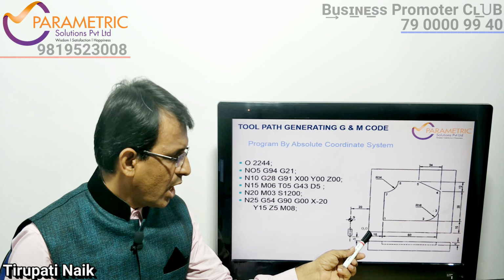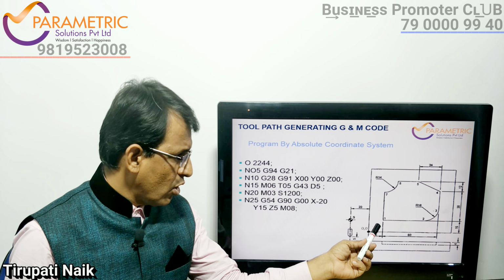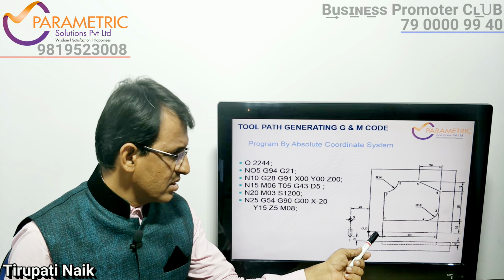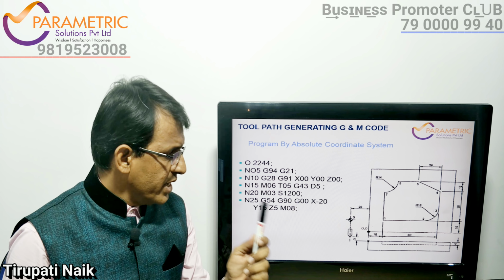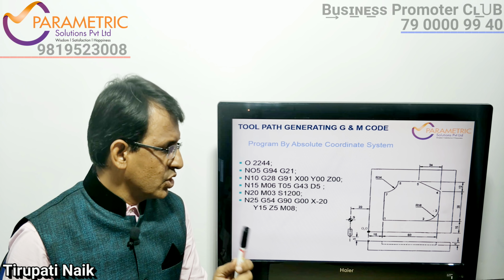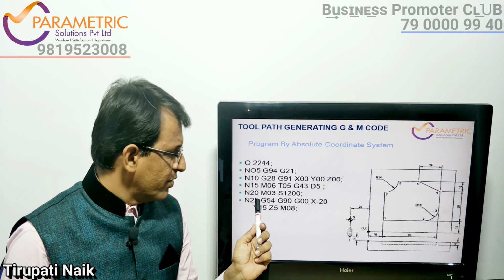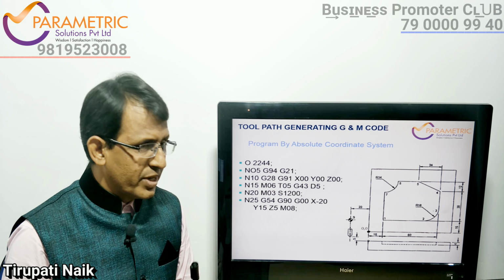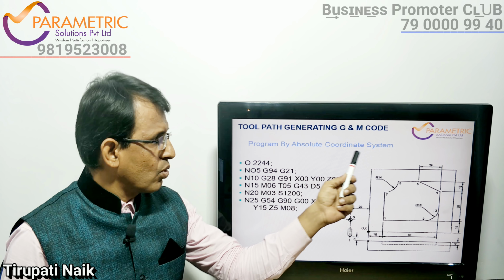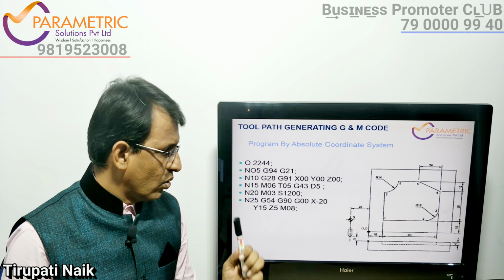At this particular point I am going to take a reference with the tool: touching the top position is Z0, then touching the bottom side face is Y0, and touching the left side face is X0. So those three values, X0, Y0, Z0, will be entered in the G54 page, that is, the offset will be taken. Then the absolute coordinate system, which is also called the Cartesian coordinate system, is the G90 code.